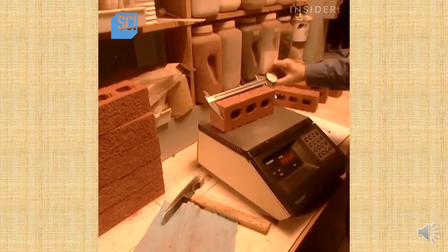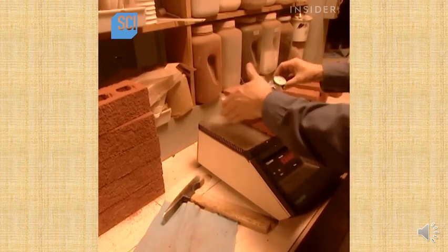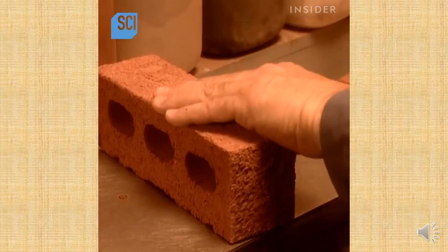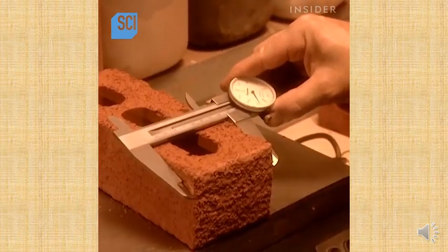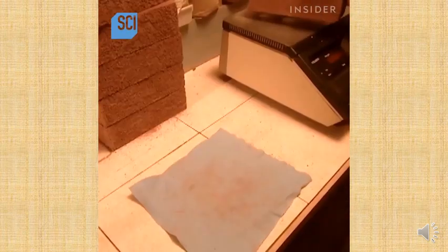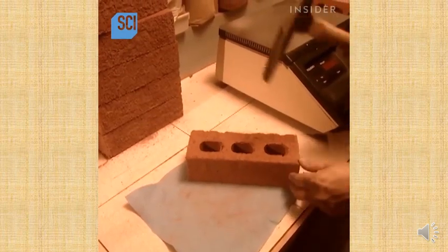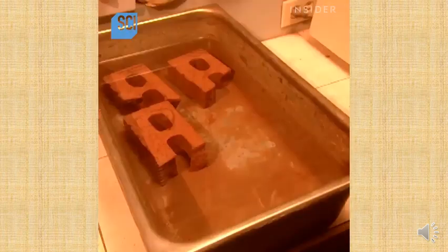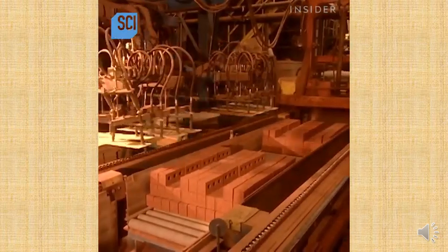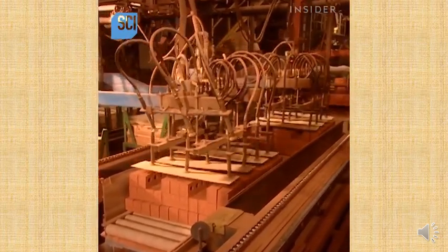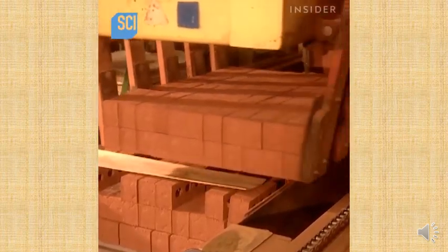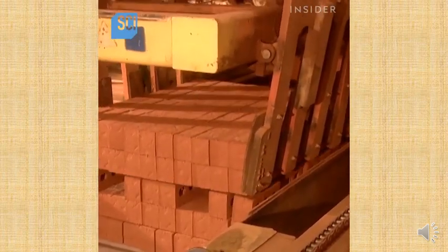Bricks are supposed to absorb some water, but not too much. Yet if they repel water completely, they'll also repel the wet mortar the masons use to stick the bricks together. So to test absorbency, the technician breaks a brick in half. He weighs it before and after soaking it in water for 24 hours. By comparing the weights, he can see how much water the brick has absorbed. Once the batch gets the okay, they stack the bricks into cubes of 500 to 600. Each brick weighs 5.5 pounds, so each cube weighs in at about 1/4 ton.